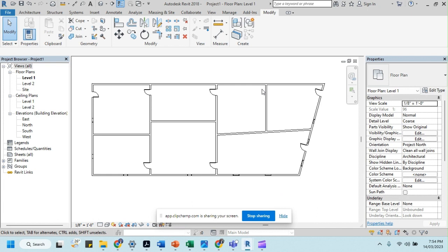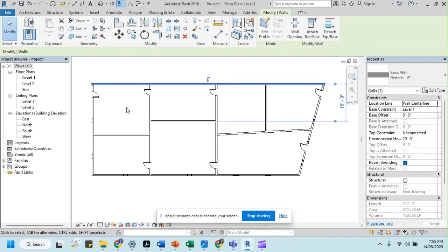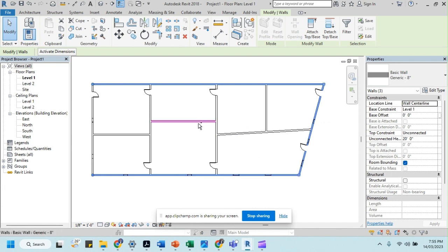It will be very useful. The first method is we can select one object at a time. As I learned previously, we can click any object and then we can see the pre-selection color. After we click, it will turn blue. That's the selection color. If we want to add another item, we can press the Control button. Then the mouse pointer will appear with a plus sign. Then we can click another item, and that item will be added to the selection. This is the method to add to a selection.